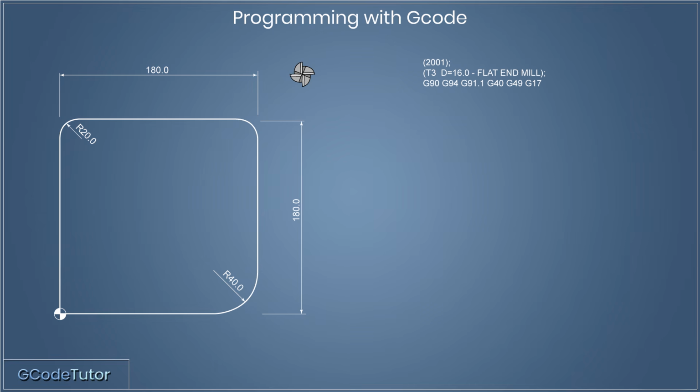G17 is our working plane. Now G17 means the XY plane, in other words the flat plane of the machine table. So Z is always up and down, and X and Y just tells the machine that we're cutting along this plane. So when we're using I, J and K values to define the center points of a radius, this lets the machine know which plane we are referring to. With CNC routers, we always work in G17, so this is always the same.